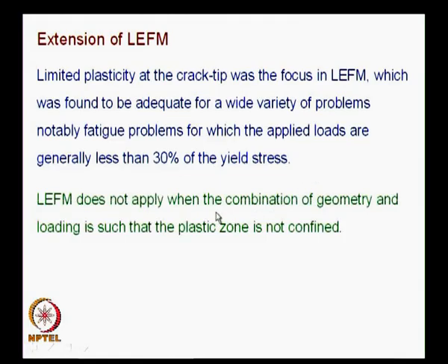So, when you have a different combination of geometry and loading, it could lead to expansion of the plastic zone. So, the plastic zone is not confined. So, in such applications, linear elastic fracture mechanics would not be sufficient. So, you have to look for newer methodologies,